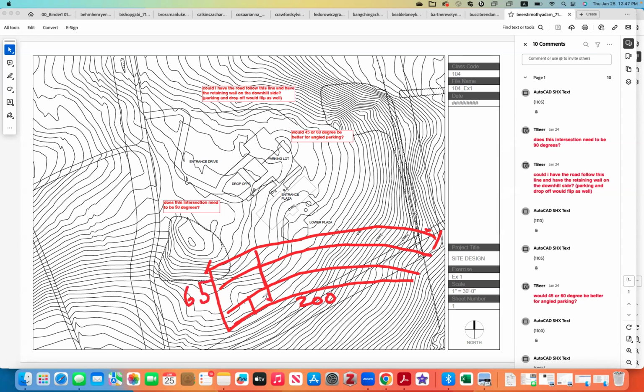I might even start with a rectangle and put it on the flat area, and then I see how much space I'm lacking. Does that make sense? If part of my rectangle starts to fall on steeper land, I start to curve the 200 feet line.